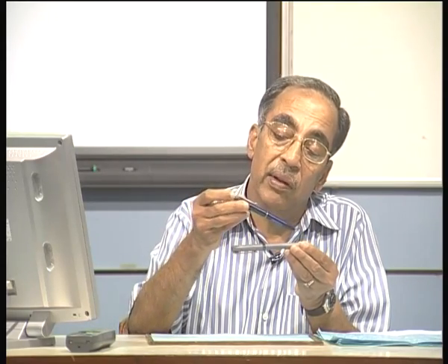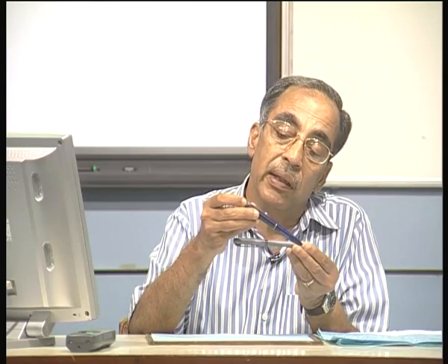I give you another example. Suppose the generating curve is a slant line, again a straight line, but at an angle. If I rotate it, I will be generating a conical surface. All right. Suppose this is a curvilinear line, a semicircle. Then if I rotate it, I will be generating a spherical body. Okay. So in this way, these are the surfaces of revolution.